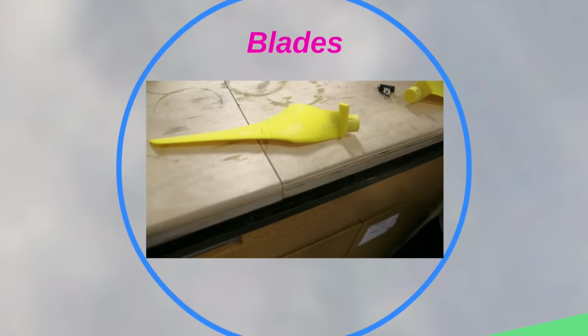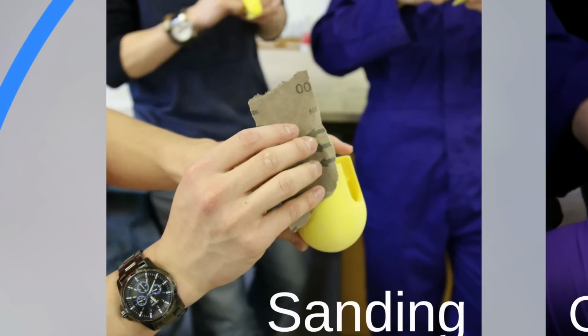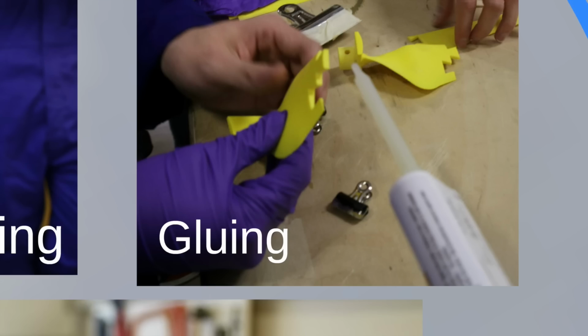The blades were 3D printed using ABS, which is a thermoplastic polymer. Each blade was printed in 2 parts and later glued together at the joint. The hubs and blades were sanded to give a smooth surface. The blades and hub were assembled using a countersink bolt.